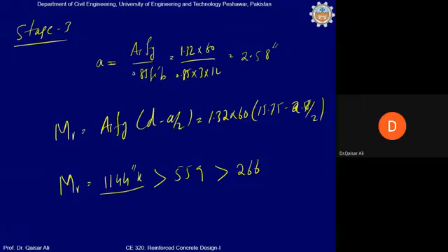अच्छा, ये तो आप कैपेसिटी कैलकुलेट कर सकते हैं, an existing beam, यानी आपके पास एक बीम है जिसकी साइज भी नोन है और reinforcement in the beam is also given to you. मगर डिजाइन में हम क्या करते हैं, in the design we don't know the reinforcement. The size will be assumed, size of the beam, for example 12 by 18 inch, it will be assumed, and then for the given demand we will calculate the design reinforcement. This is what is called reinforced concrete design. बात समझ में आ रही है कि नहीं?